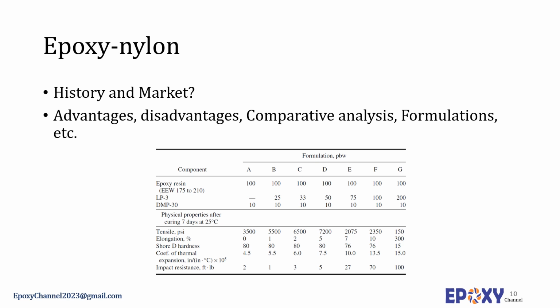These characteristics are achieved by blending epoxy resins with copolymers from the polyamide or nylon resin family, which is noted for toughness and tensile properties. A commercial example of an adhesives grade nylon is DuPont's Zytel 61.